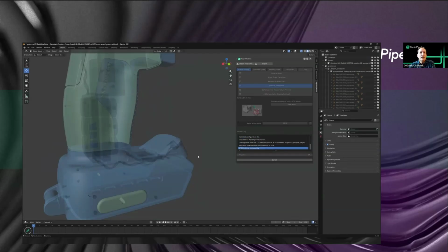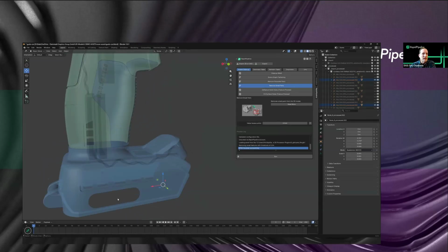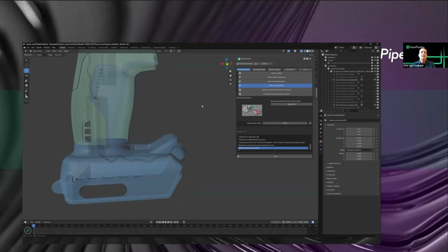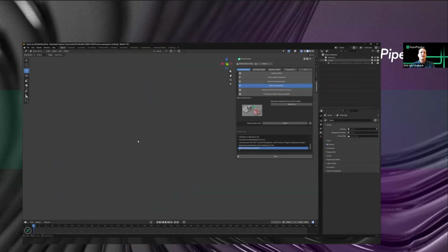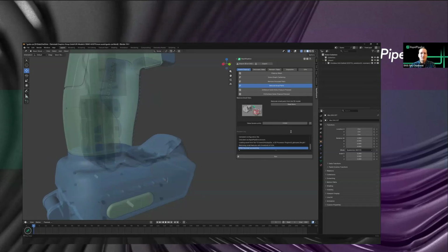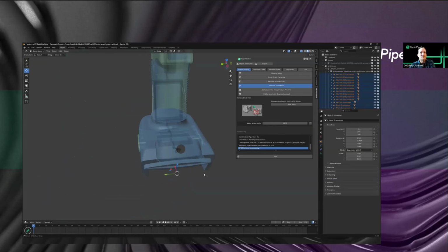Excuse me. And again, it's a very iterative process here. If I don't like what it did, it actually pulled out a larger piece that I didn't want it to remove. So I could basically go ahead and redo this work very easily by just hiding or deleting the parts that I don't want, getting back to the original without having to re-import it all. So let's choose, say, 3 centimeters. That might be a better value to choose. Then we can iteratively get back to what was the right value to cull away those small parts.